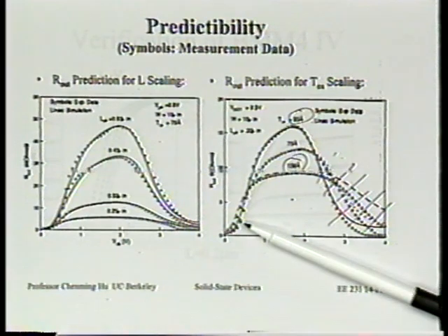Why does it have, please speak into the microphone, please. I think for the thin oxide, the DIBL effect will be more tremendous than the thick oxide. All right, so you're commenting on the DIBL effect. So you say for thin oxide, DIBL effect is stronger or weaker? For thin is stronger, I'm sorry. For thin oxide, you think DIBL phenomena is stronger, huh? Okay. For thin oxide has the effect of suppressing DIBL.